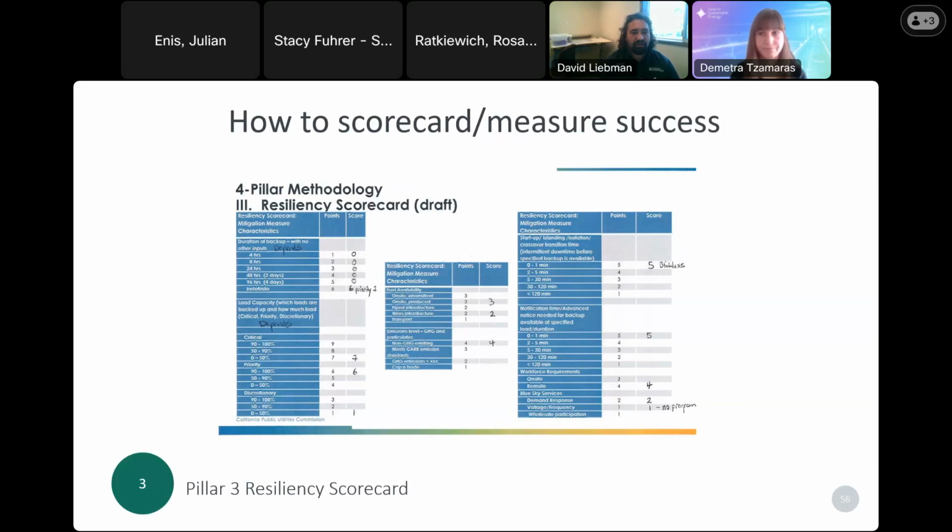We found that if we were going to prop up our entire campus without load shedding, we could do a 3-hour event, but we couldn't do a 4-hour event. If we load shed, we can serve our priority buildings, our load priority 1 buildings, indefinitely with solar and battery. And we can then serve our load priority 2 buildings, really dependent on the month of the year and whether or not we are experiencing our peak months. Our load capacity was hard for us to figure out since it really depended on the time of year and whether or not we were load shedding.